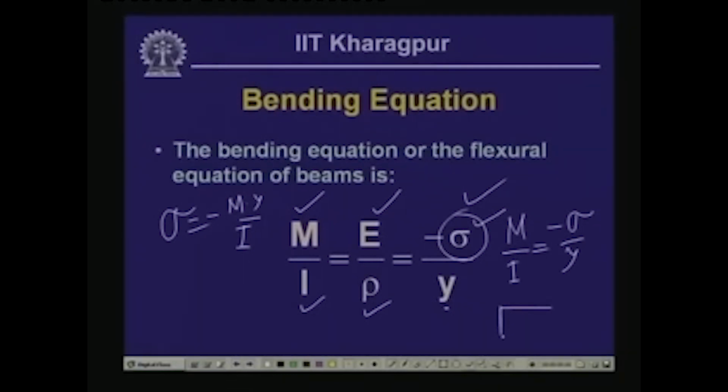If we take the segment, the positive bending moment in the beam was like this, wherein this type of moment causes compression at the top and tension at the bottom. Because of the bending acting on this segment, the bottom fibers undergo stretching, which is tensile, and the top fibers undergo compression, which is compressive.